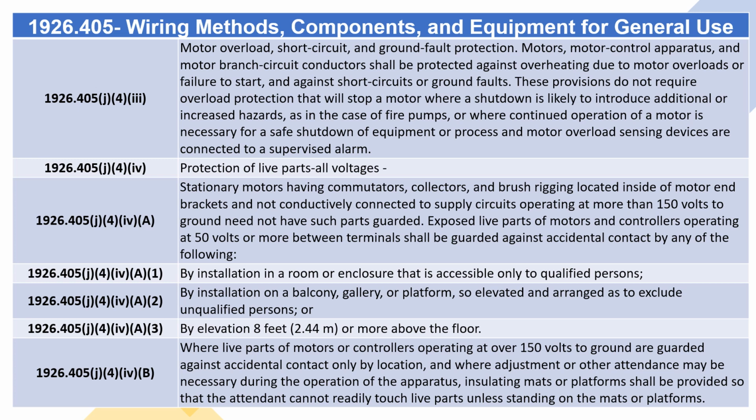By installation in a room or enclosure that is accessible only to qualified persons, by installation on a balcony, gallery, or platform so elevated and arranged as to exclude unqualified persons, or by elevation 8 feet (2.44 meters) or more above the floor.